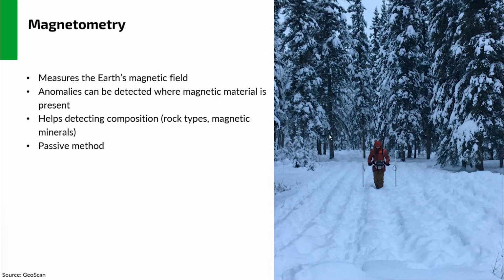The reason why this is helpful is because the Earth's magnetic field changes even during the day. So you can eliminate all the corrections needed in order to properly create a magnetic anomaly map. Gradiometers help to eliminate those needs.